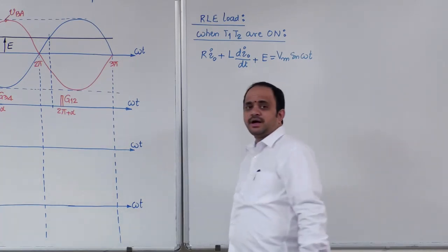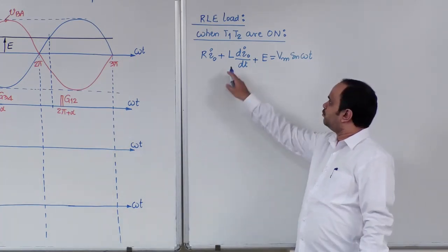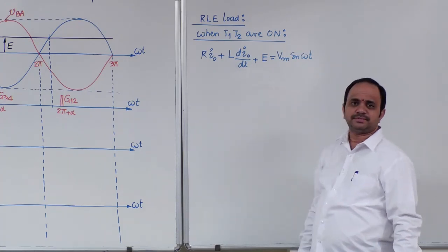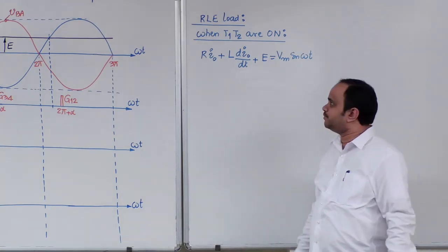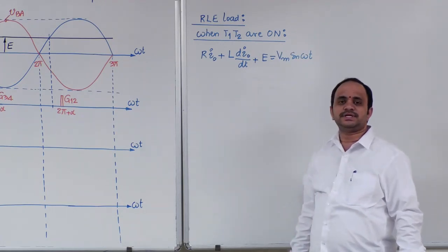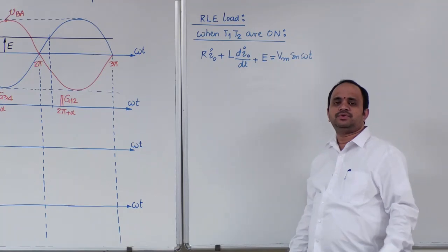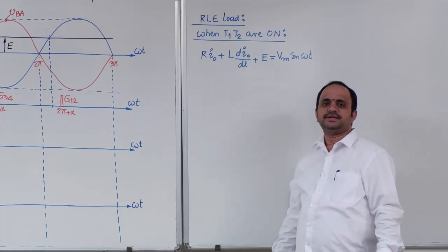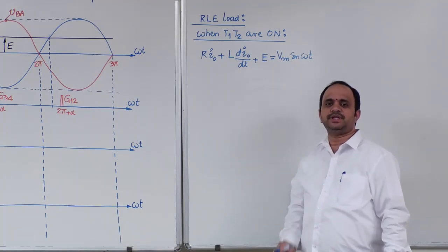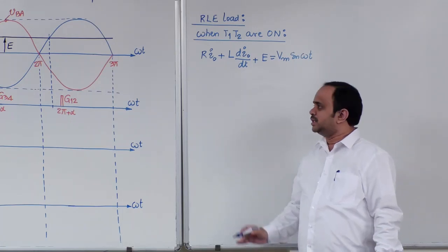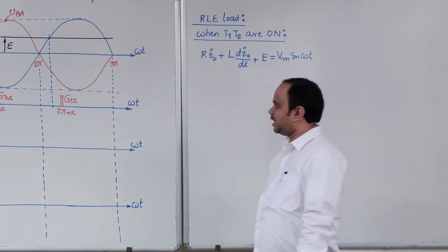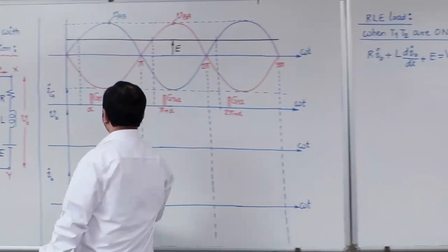So in our earlier half-wave rectifier circuit, we have solved this equation. Okay, we had some lengthy equation. From that, what was the conclusion? Output current will have two major terms. One is sinusoidal, another is exponentially decaying component. Therefore, first let us draw the output current waveform.